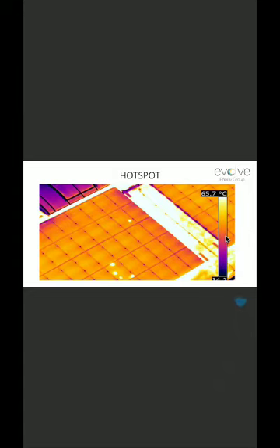When a cell is falling under a shadow, or when the cell is not producing any power, when the cell loses its efficiency, then the cell starts consuming the power which is generated by other cells. So look at this yellowish cell that starts consuming power from other cells. If it starts consuming, there is no point to utilize the power in the cell, so mostly that will be a heat loss.